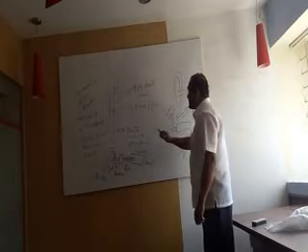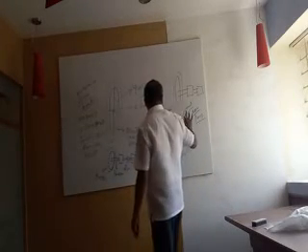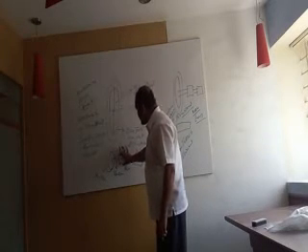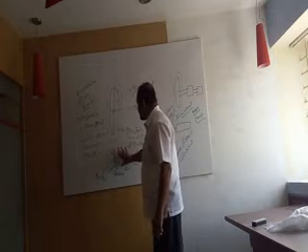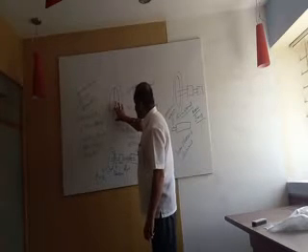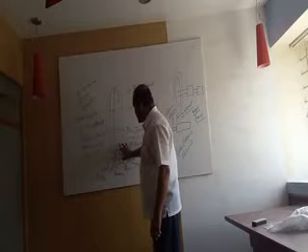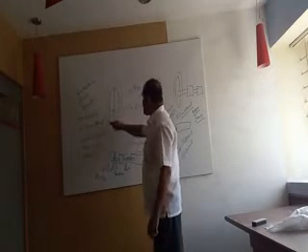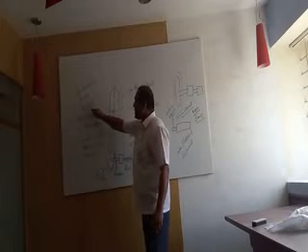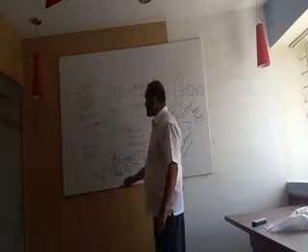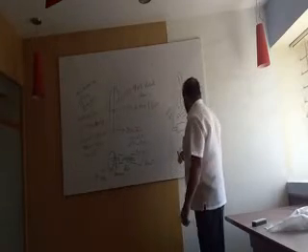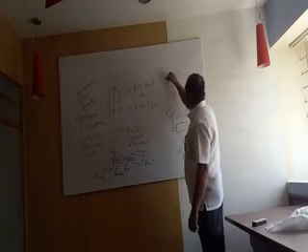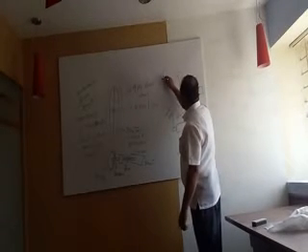This flywheel is not connected directly to the generator. It is connected via a speed decreasing gearbox, a speed reducer. Here the speed reducer will keep on rotating. The inlet shaft of the speed reducing gearbox will have the 800 ton flywheel rotated at 1500 RPM using 8 megawatts or 8000 kilowatts of energy. This part is separate, and this application will have a cylinder with a piston.